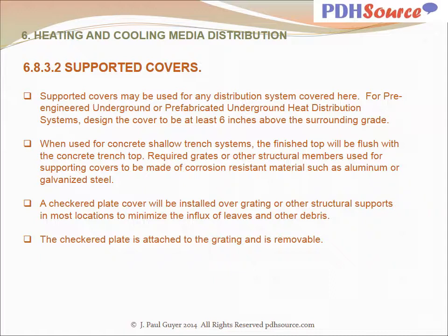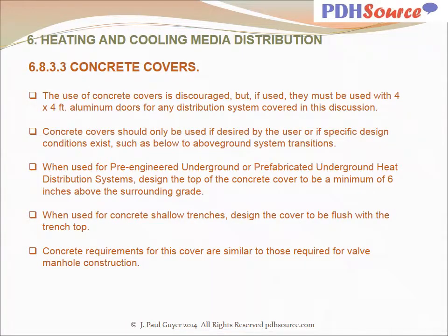Required grates or other structural members used for supporting covers shall be of corrosion-resistant material such as aluminum or galvanized steel. A checkered plate cover should be installed over gratings or other structural supports in most locations to minimize the influx of leaves and other debris. The checkered plate is attached to the grating and it is removable.